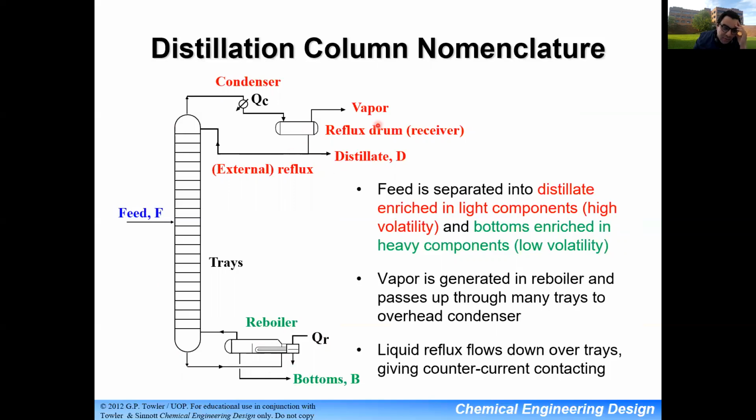And from the distillate, you have a reflux drum. So the idea of a reflux drum is to try and condense some of the heavier ends from the distillate and recycle them back to the column. This could flow this way or could flow this way. So the arrows here show it this way. And then you have some vapor product, and you usually have a heat exchanger called a condenser before introducing your fluid to your reflux drum. And sometimes on your process diagrams, this heat exchanger could be represented here, but the idea is the same.